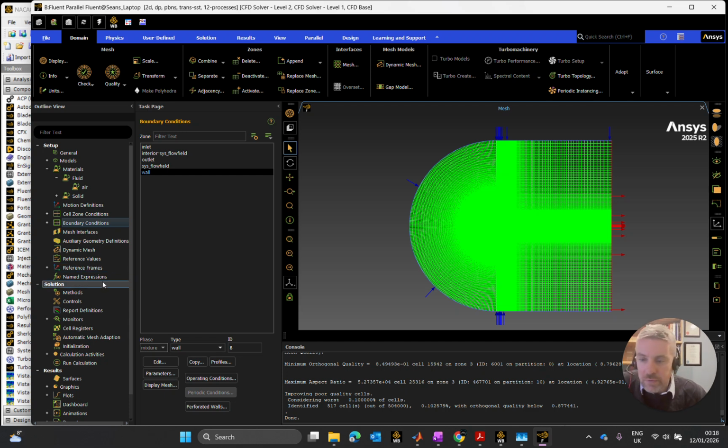I try to plot that profile, and instead of putting a single magnitude into the inlet boundary condition, when I run the transient condition, I'll write an expression. That will either be a user-defined function, a separate piece of C code that I'll bring in and parse in this software, or else you could write it as a named expression potentially.